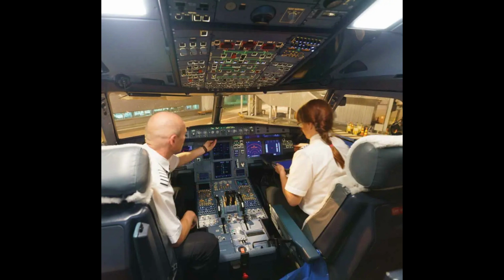3. Verify that desired track is being followed by the aircraft. 4. Verify that the correct navigation source is selected to guide the autopilot's track. 5. Be ready to fly the aircraft manually to ensure proper course/clearance tracking in case of autopilot failure or misprogramming. 6. Allow the FD/autopilot to accomplish the mode selected and programmed without interference, or disengage the unit.